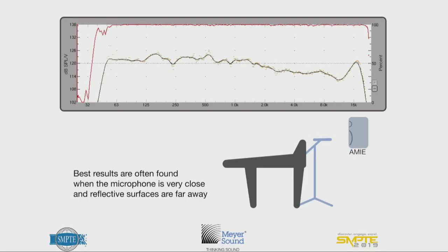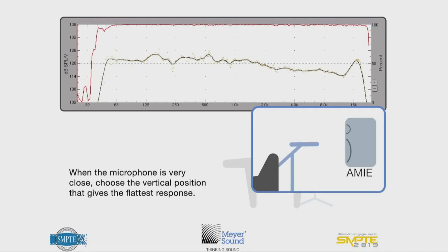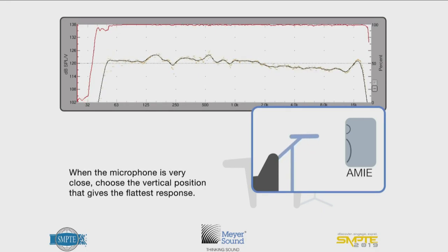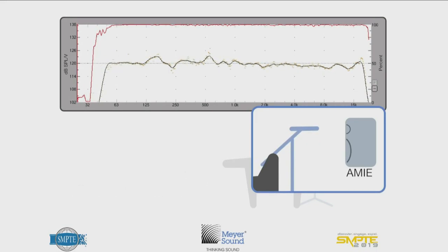The rest of the procedure, which I'm about to show you, is agnostic about the frequency response. You just need to see the whole bandwidth of the speaker, all the frequencies the speaker is producing. And then what we're looking for is a change. If you turn up the signal, does that response stay the same or does it change? So here we go. We're going to move our very close microphone up a little bit, and we'll see that we can get a response that is relatively similar to what we hope the response is in the far field.